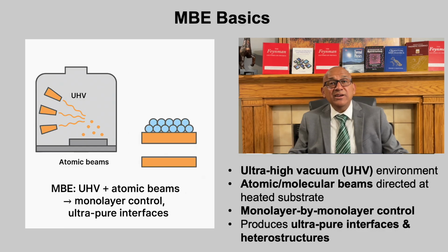MBE takes place in an ultra-high vacuum chamber where atomic or molecular beams of source materials are directed toward a heated substrate. Because the environment is so clean and deposition rates are deliberately very low, MBE allows monolayer by monolayer control of film thickness. This precision enables the fabrication of ultra-pure interfaces and heterostructures, making MBE indispensable in advanced electronics, optoelectronics,